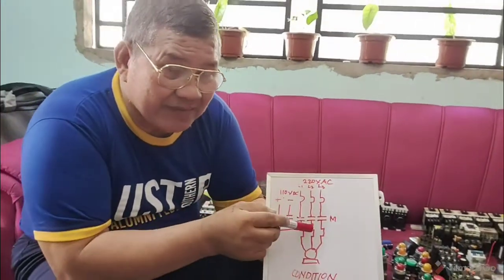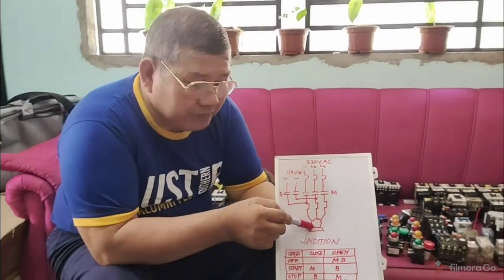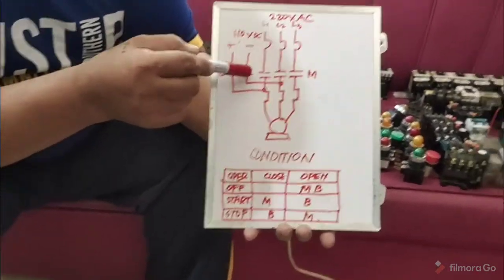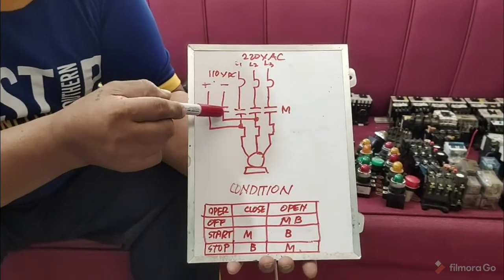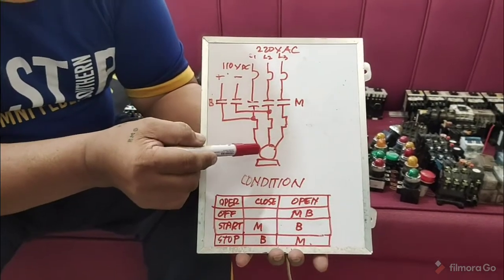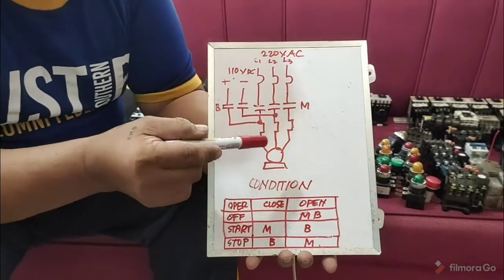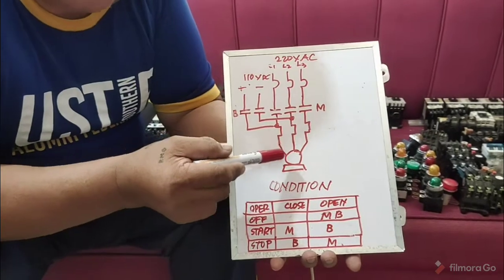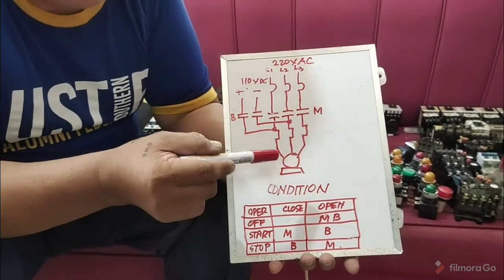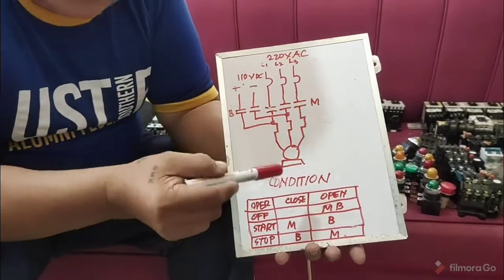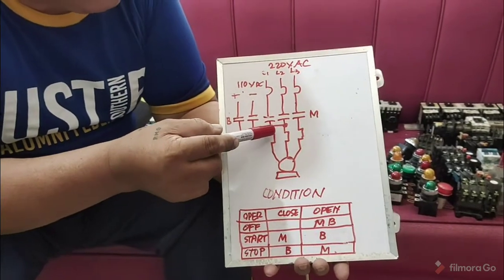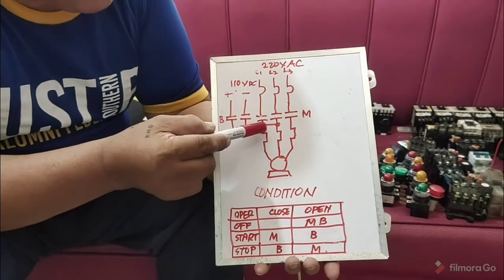If this is a three-phase motor, you just simply connect the brake contactor parallel to line 1 and line 2. Meaning, you are simply energizing one phase of the three-phase motor. Energizing one phase using a DC contactor is enough to stop the motor quickly. If you don't want line 1 and line 2, you can use line 1 and line 3.